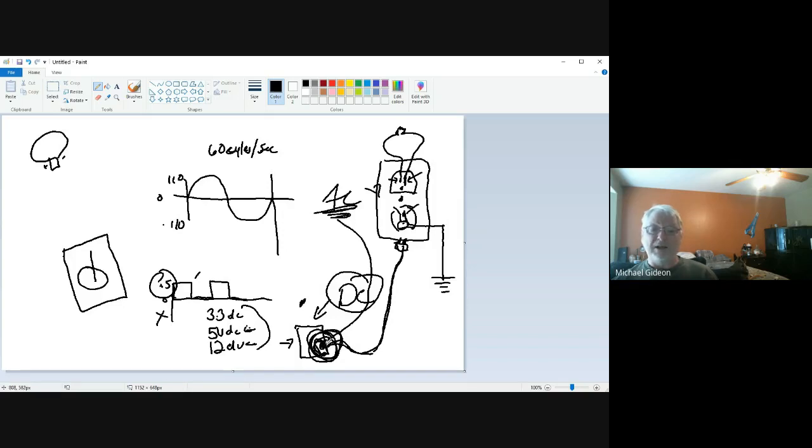Once you're beyond the power supply, those cords that are coming off, a typical power supply will have a plug on the back, and it'll come off. It's detachable. And then on the other side, depending on how big your power supply is and how many watts, we'll have the connectors. And these connectors will either be 3 volts, 5 volts, or 12 volts. Now, the connectors have a bunch of wires on them, and each wire might do something different. Only one of these would have power on it. The others do something, a return line or a signal or something like that.